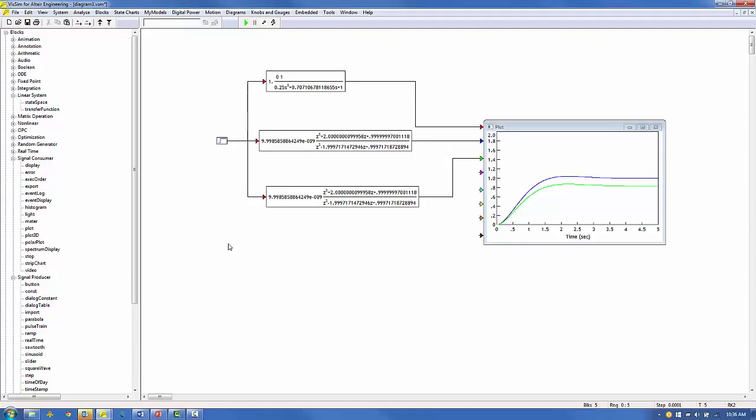Well, this looks better, but there's still significant transient and steady-state error between the discrete fixed point and the other two. Why is this? The transformation used to convert continuous transfer functions to discrete transfer functions contains the discrete sample time in its gain.